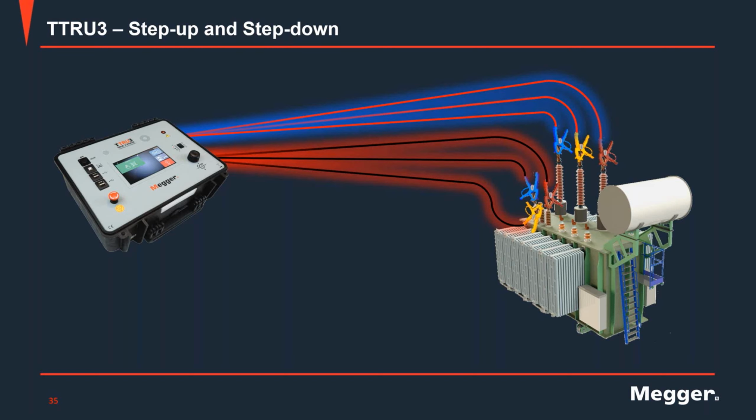As you can see, I'm going to go back, right? So my red glow is indicating which side of the transformer is being energized. This is the traditional way, step down. When I go to step up, I'm energizing the low voltage side of the unit. And remember, every transformer will show some voltage dependency, some obviously with a higher degree than others. And this has to do with the core material, the windings, type, and construction, right?